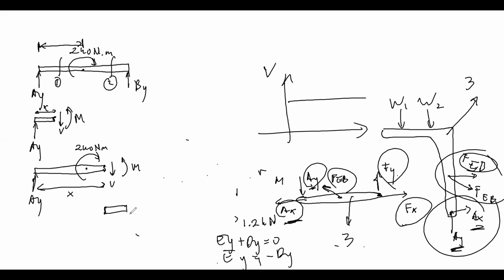Okay, and we have Py here. Because the force and moment are happening on the left of the cutting, which way is the positive side supposed to go for shear force? Shear force would be going up. Yes, it's correct. Shear force is supposed to be going up. How about the moment, clockwise or counterclockwise? Clockwise. Correct. Something like this.